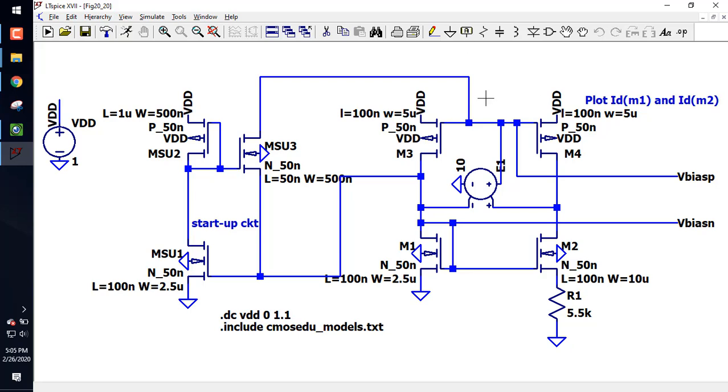One more time. Does everybody agree that if this node goes up, it shuts off the VSG of the transistor? Does everybody agree that if that happens, it shuts this transistor off? If it shuts this off, doesn't it allow this node to go down? So doesn't that mean if this is going up and this is going down faster than this one's going down, that I'm going to get negative feedback through here? This going down in the negative direction will be added faster than this one going down and have a net negative effect. So I know that's confusing, so let me try numbers.